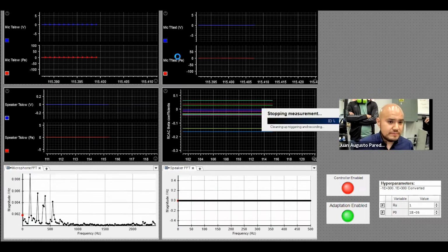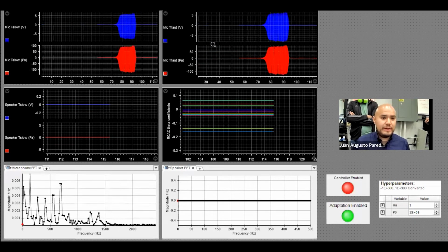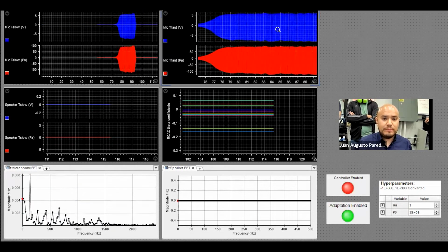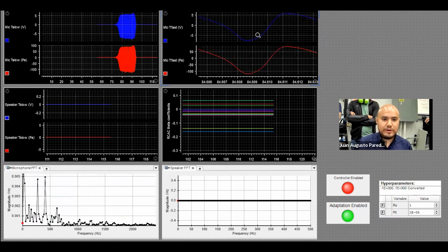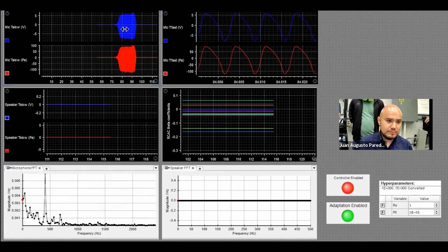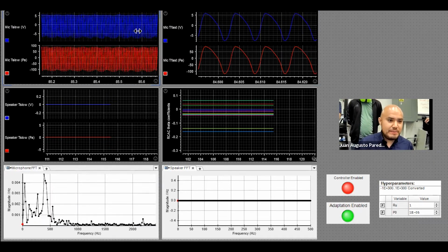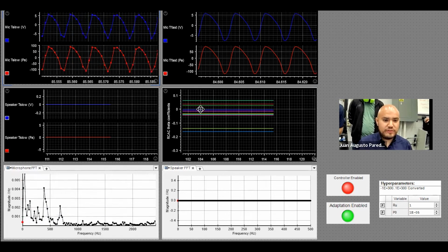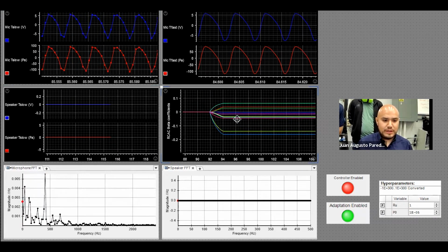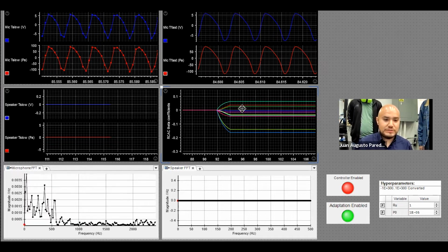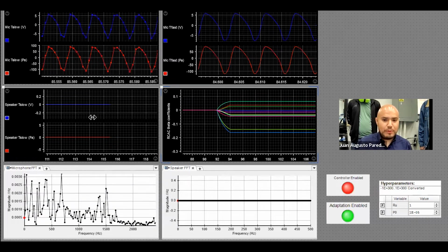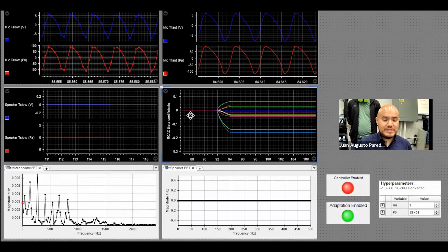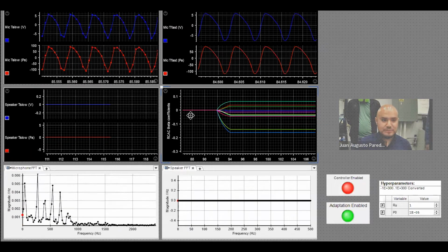In this case, the oscillations were different from the position at the higher coil position. However, RCAC still managed to quite swiftly figure out a set of parameters that were suitable for this application. However, this is in a case with lower voltage supplied. Now we'll supply 95 volts and you'll see a significant change in RCAC response.